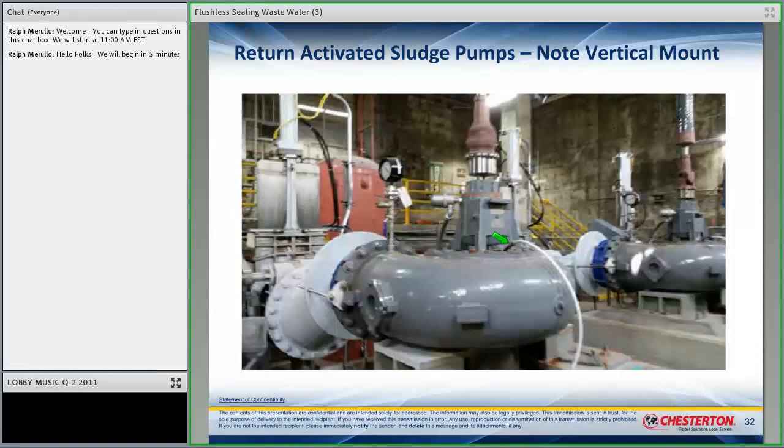See this line? That's your suction reserve. What you would expect to see is, if there is fluid up to, say, this point in a seal chamber, when you start the pump you'll start to see gas bubbles coming out here and everything will be fine. The seal will be immersed in fluid. When they started these pumps up, we never saw fluid. That's a problem. The whole casing was full of gas.